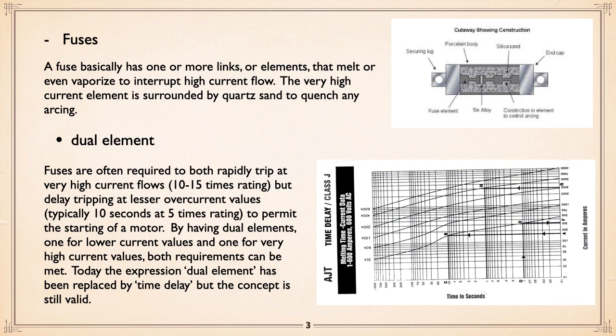Fuses, basically a link, whatever, that melts under high current. Once it hits a certain level, it will actually melt it, if not vaporize it completely. And the element within the fuse is surrounded by silica sand, which helps dissipate, get rid of any arcing that occurs.